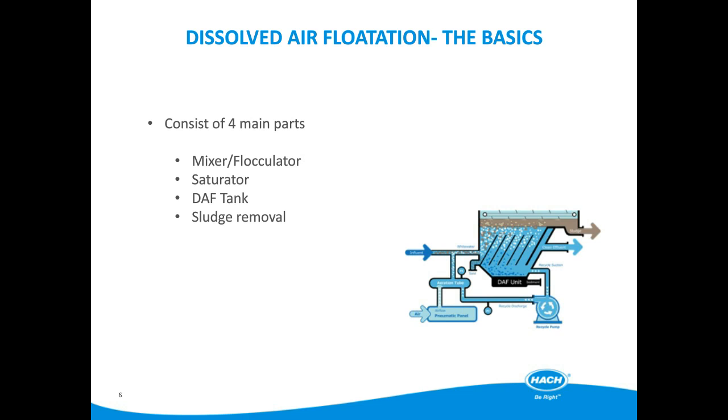The DAF tank itself is where the solid separation occurs. Note, some solids are not floated and do settle into the base of the DAF tank, so sludge collection from the base of the DAF is required. Floated sludge is removed by a skimmer or scraper and transferred into a hopper for further concentration. The DAF schematic shown on this slide shows the settling sludge being thickened by a lamellar separator. Other designs may simply use conical sludge collectors or similar.